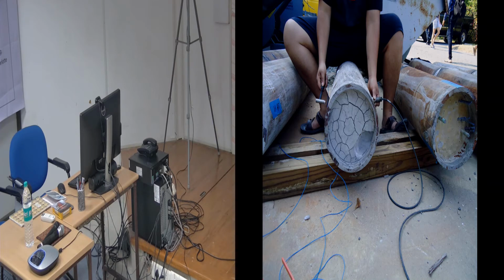When you do impact testing, you are exciting the whole structure. When you impact onto the structure, this is the input, and you will receive a response. The time difference between the two arrivals is the wave traveling. But the response carries a lot of the characteristics of the vibration of the system. And you're right, if we take this and convert it through a Fourier transform, you will get a lot of those modes, and those are vibration modes. So we use the time of arrival to do the wave propagation, and then use the response to do the vibration.